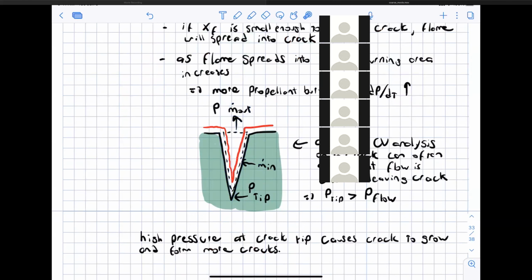You know that this is a constant or variable area duct. So this would be a bit like a gas dynamic nozzle where you have mass injection. That's one of the classic configurations. You might learn that in gas dynamics, maybe not. Certainly not in introduction to compressible flow, but in gas dynamics you might. But anyways, even with this mass injection here, you cannot spontaneously accelerate a flow beyond a supersonic condition, especially with the diverging area, and so that same rule still applies.